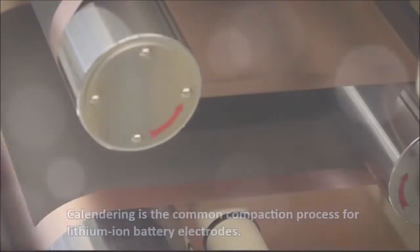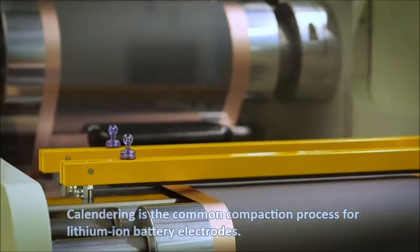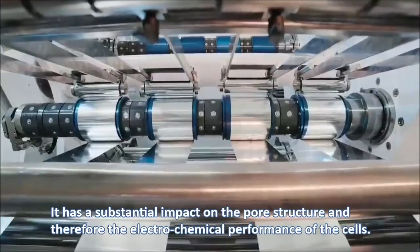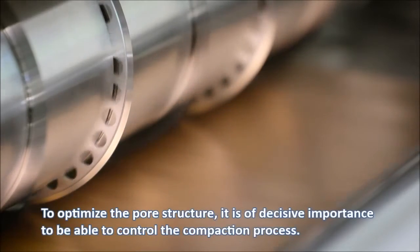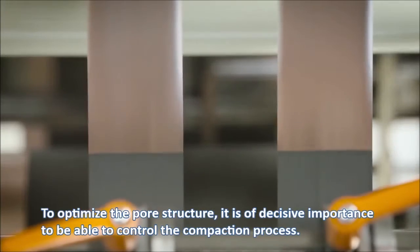Step 3, calendaring. Calendaring is the common compaction process for lithium-ion battery electrodes. It has a substantial impact on the pore structure, and therefore, the electrochemical performance of the cells. To optimize the pore structure, it is of decisive importance to be able to control the compaction process.